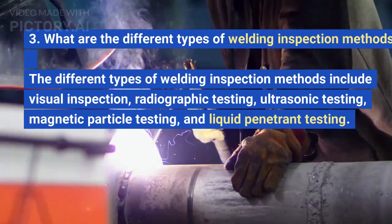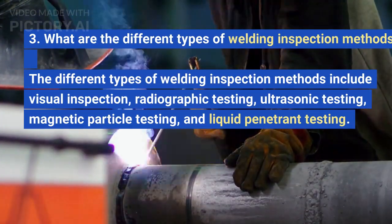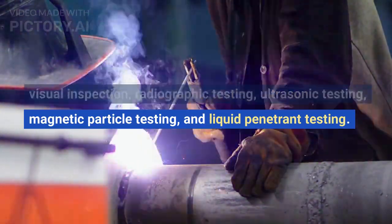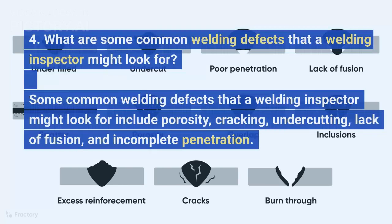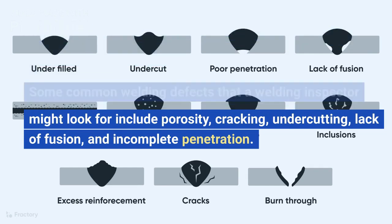The different types of welding inspection methods include visual inspection, radiographic testing, ultrasonic testing, magnetic particle testing, and liquid penetrant testing. 4. What are some common welding defects that a welding inspector might look for? Some common welding defects that a welding inspector might look for include porosity, cracking, undercutting, lack of fusion, and incomplete